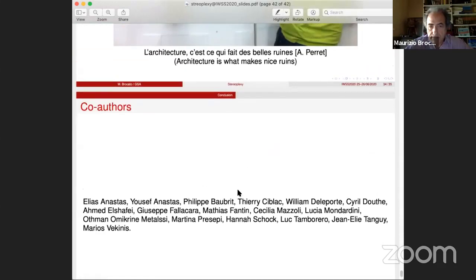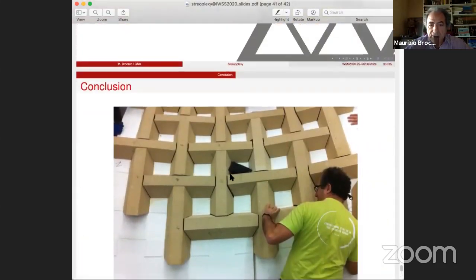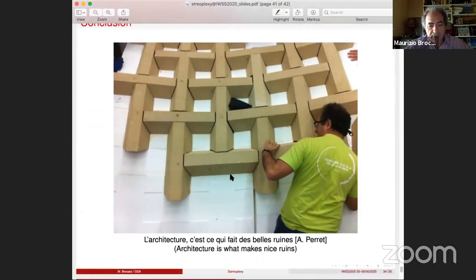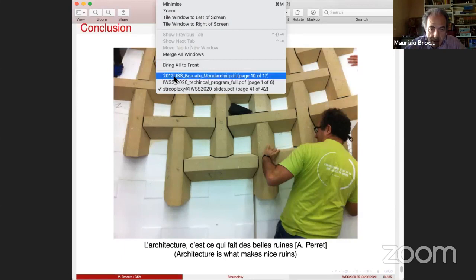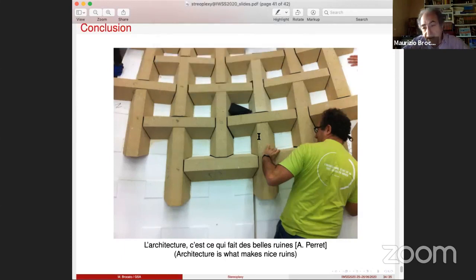Yes, thanks to the shape, the thrust on the support is much reduced. And we have made some analysis to understand how the shape of the blocks could affect the thrust, and if there is such an effect. If you read the treatises of the 18th century, there is a long debate about the wedge effect and the catenary effect, which one is dominant, for instance, in a flat arch. And actually, you understand that there was something missing in their reflection. That is, they were missing the knowledge of mechanics of elasticity, which wasn't there. This is a bubble diagram that shows compared computations on.